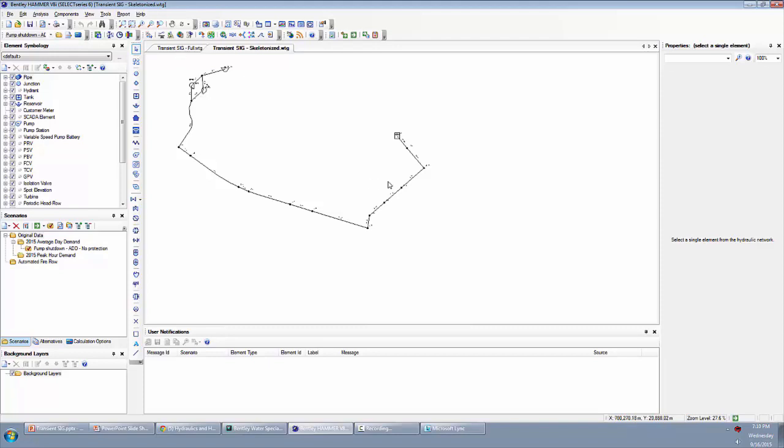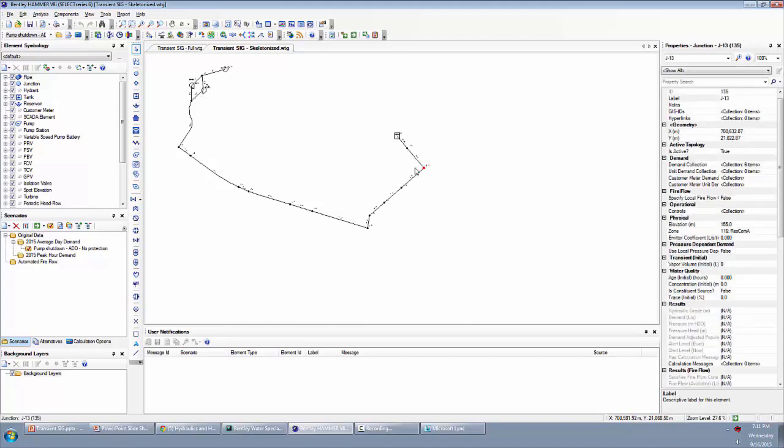They're hydraulically equivalent. So if you have Bentley WaterGEMS, you can take advantage of the Skelebrator tool and pretty quickly simplify the model down. What that does is it creates, like I said, a hydraulically equivalent version of that full model by basically lumping your demands on the elements that are left over. If it has to combine any pipes in series or parallel, it combines them in such a way that they're hydraulically equivalent. So you can see, for example, at this junction, there's six demands that are contributing to that, and those were at one point further downstream.